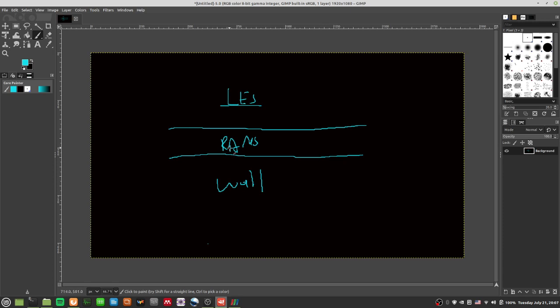Reynolds averaged Navier-Stokes actually performs better for forced flows, where you have a pressure driven flow or velocity driven flow or some free stream, that kind of thing. It works well closer to the wall, especially when you have fully developed flow. Now of course, in the middle you have sort of a blending region between the RANS and the LES, the Reynolds averaged Navier-Stokes and the large eddy simulation.